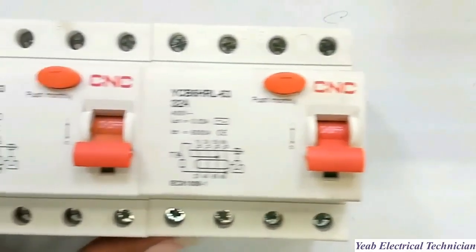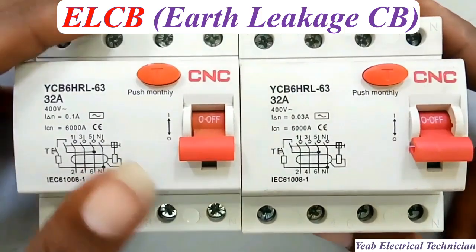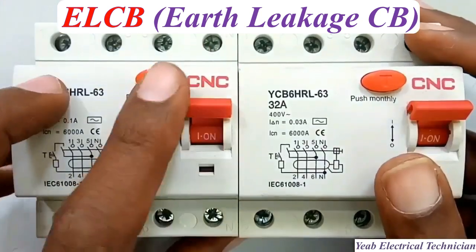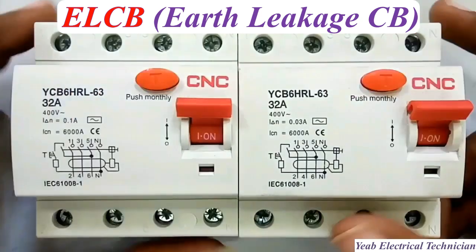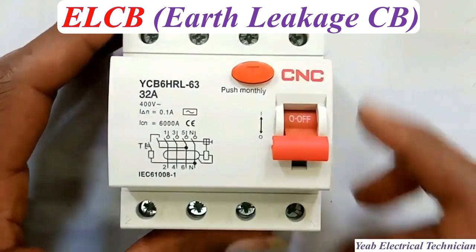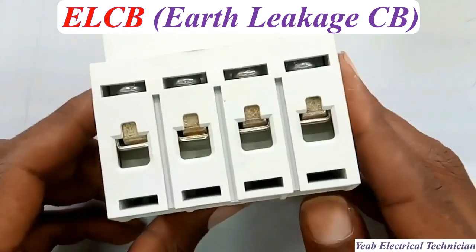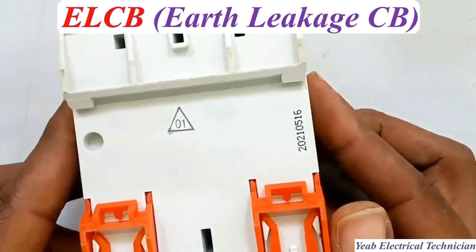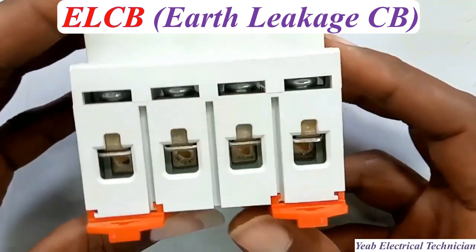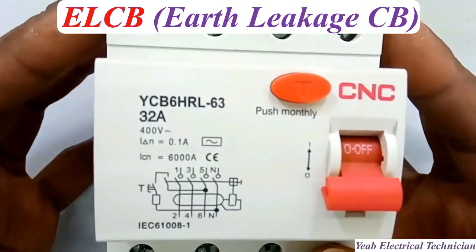An ELCB, which is an earth leakage circuit breaker, is a safety device that protects against electric shock and fire by detecting and interrupting dangerous electrical currents that leak to earth. It does this by monitoring for an imbalance between the current flowing into the live and neutral wires, or by detecting stray voltage on the equipment enclosure. The ELCB constantly monitors the electrical circuit for any current that is flowing to the ground through an unintended path, such as a person or a faulty appliance.